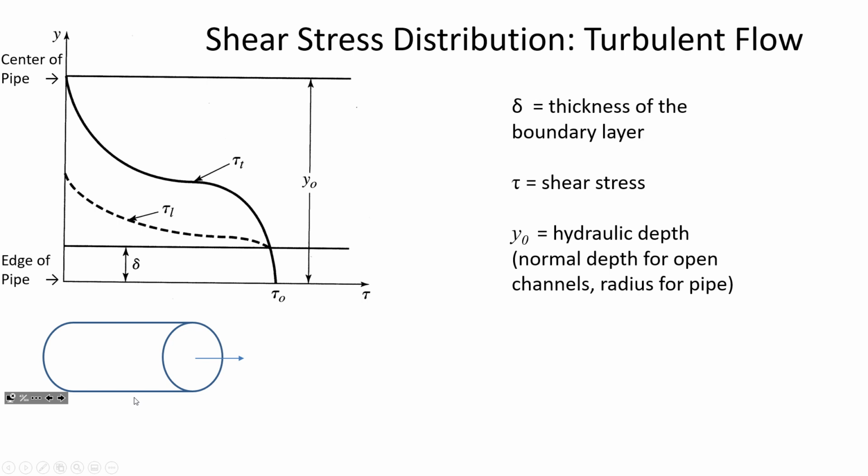I don't want to call it a force field, but this stationary pipe is exerting a shear stress, like a resistance, on the fluid. So up right at the border between the metal and the water, that's where the resistance is the highest. But then the further away you get from this bottom aspect of the metal, the shear stress is decreasing. And so that makes sense why the velocity would be highest at the center of the pipe. This is just kind of graphing for us how much shear stress is exerted on the water as a function of the distance from the center of the pipe.